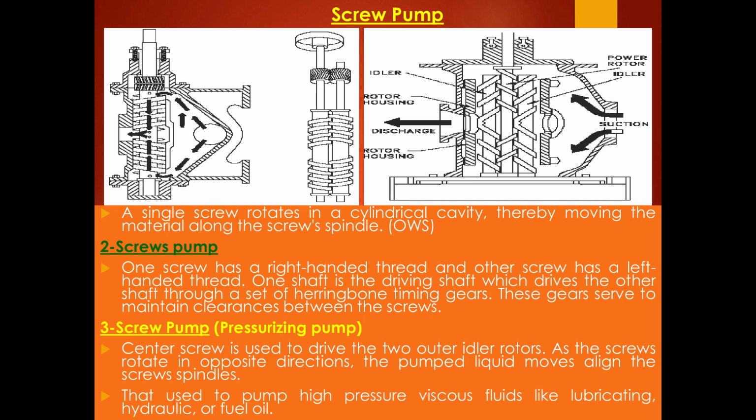Three screw pump, a pressurizing pump. The center screw is used to drive the two outer idler rotors. As the screws rotate in opposite directions, the pumped liquid moves along the screw spindles. It is used to pump high-pressure viscous fluids like lubricating, hydraulic, or fuel oil.